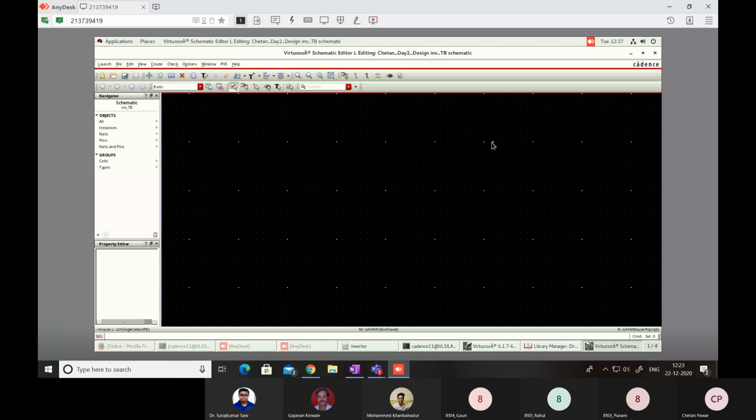Now go to the library manager. On the bottom there will be the library manager window open. Yes, good. Select that library manager. Now in that you can see for your particular cell, one view is created, symbol view. Now there are two views, symbol and schematic, right? So two views are created. Now your symbol for inverter is created. Now we need to create one test bench file. Make sure that whatever library you have created, that gets selected. If library gets selected, there is a background square around it, means it darkens, right? That name is darkened.